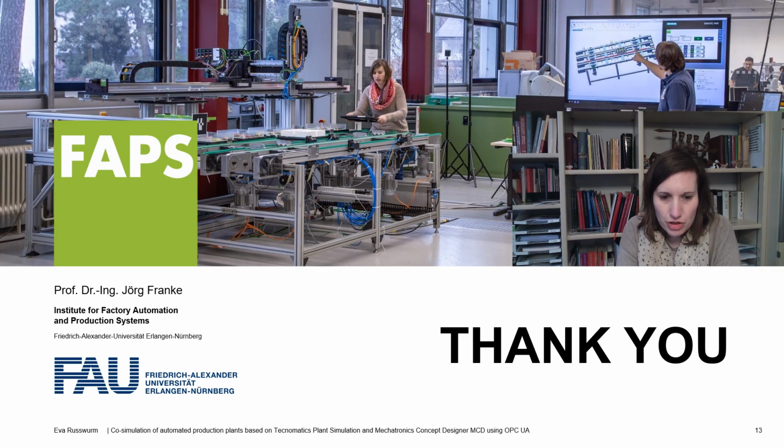As the presentation showed, co-simulation or distributed simulation can be used not only to simulate different aspects of the plant in different environments and tools, but also to perform virtual commissioning. Plant simulation in this case offers all prerequisites for virtual commissioning according to software in the loop with PLC Sim Advanced. Certainly, there are still many aspects that can be improved here. One step that we are currently working on is to perform the simulation of electronic engineering components with MATLAB, adding another tool to the co-simulation.